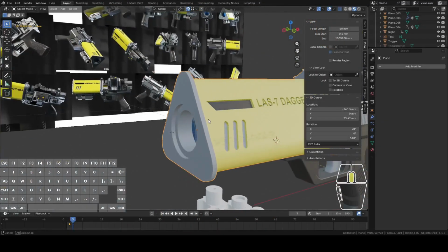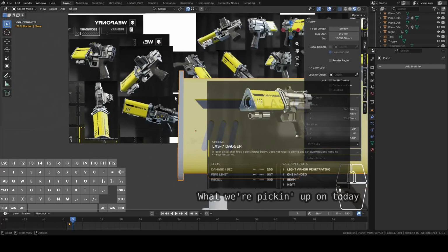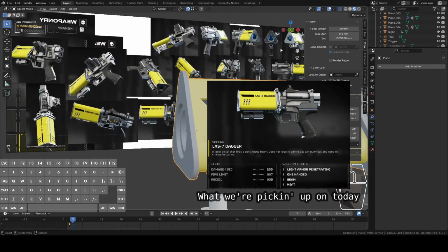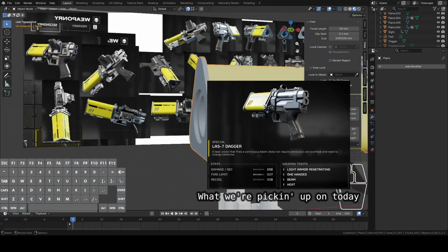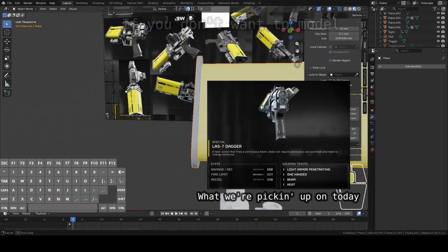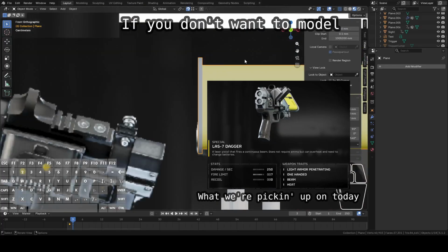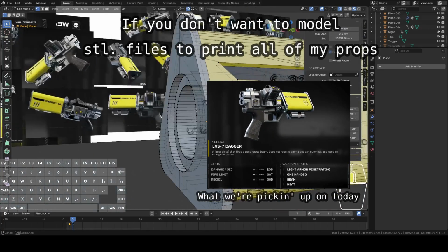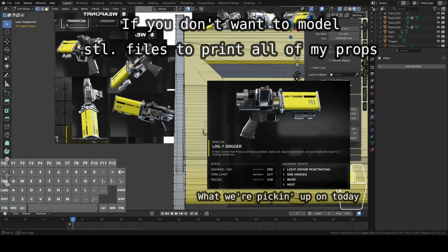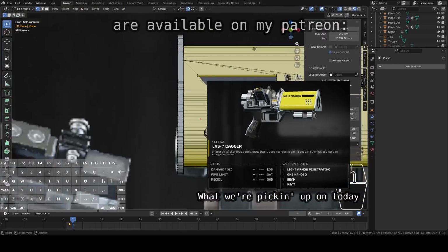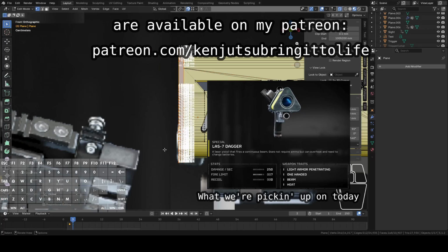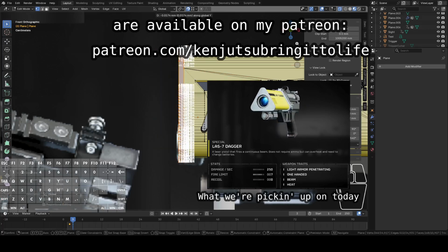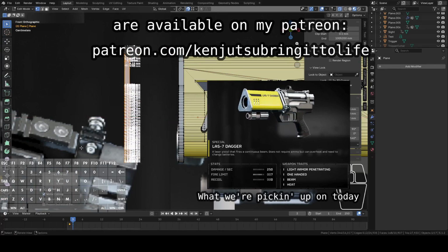It occurred to me that instead of making this whole thing a segment, you can attach and detach and kind of slide in there. I could just remove this silver bit here. So I think that's what I'm going to do. Let's see. So let's just take this whole thing, Shift D to duplicate, GX to move it a bit up here.